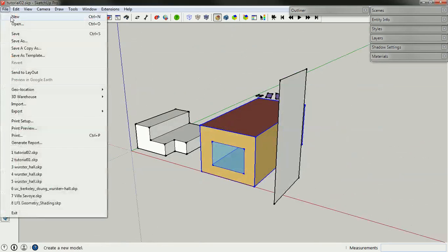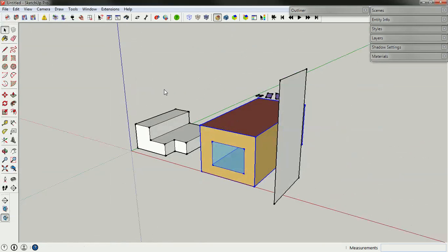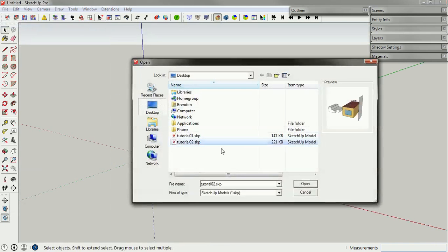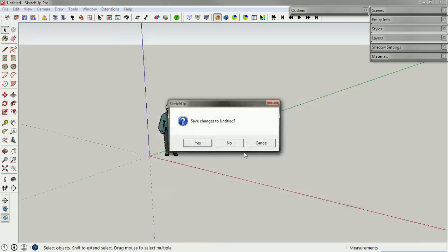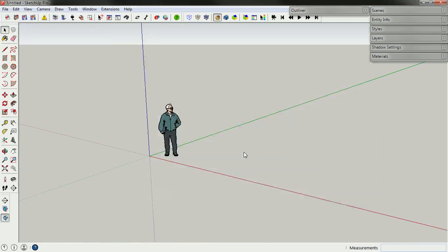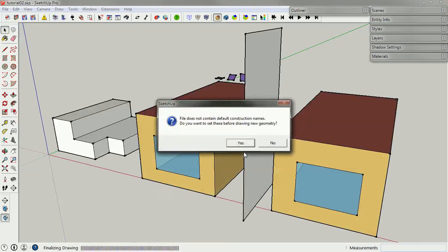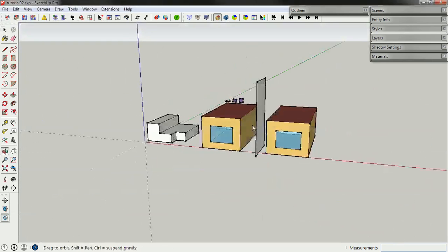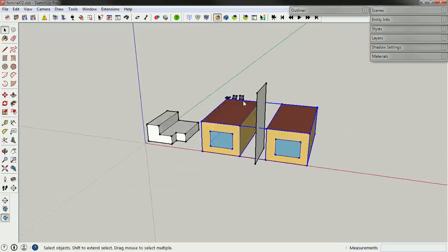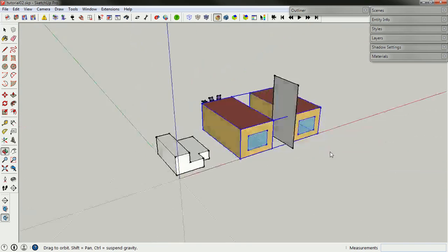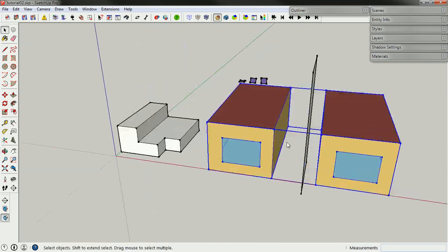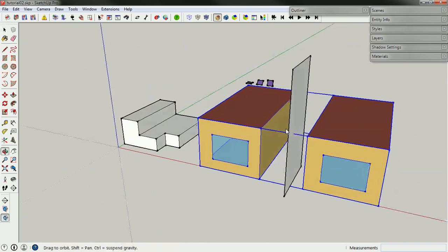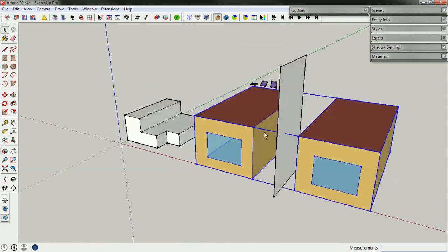And so just to make this clear, I'm going to open that tutorial2 file, and you'll see that my OpenStudio objects come back, and it's very likely you're going to get all sorts of weird errors, which I'm seeing right here. And so you never really want to save the IDF files as SKP. Always keep the two separate in your head.